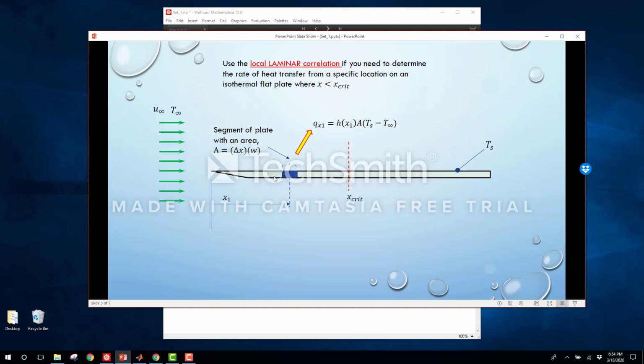So if we are interested in the amount of heat transfer from a relatively small region of the plate, say we'll use the term delta x to define a relatively small length region with respect to the total length of the plate, or in this case, the length of the plate from the leading edge to x critical. Then if we can determine the local heat transfer coefficient, we can then determine the amount of heat that is leaving this localized portion of the plate.